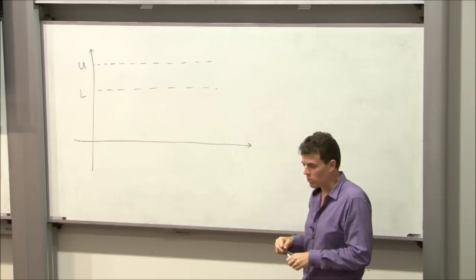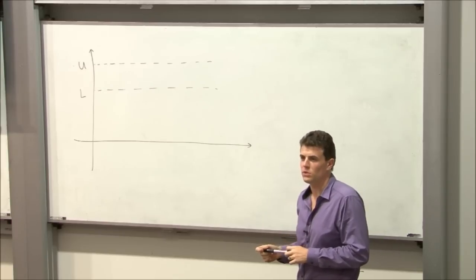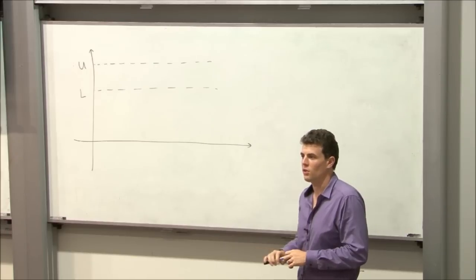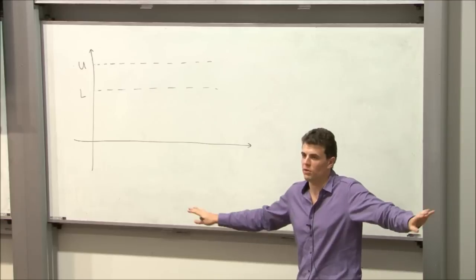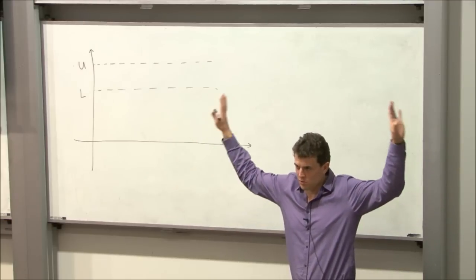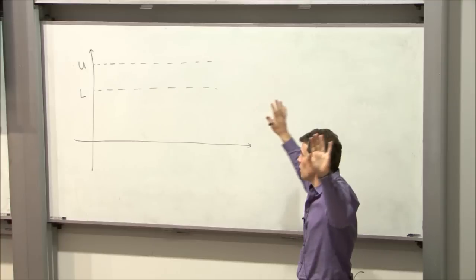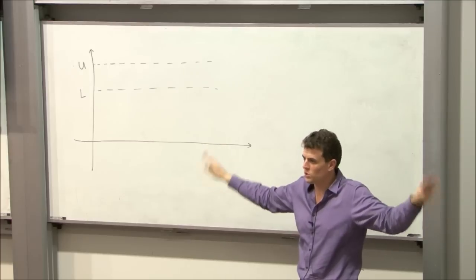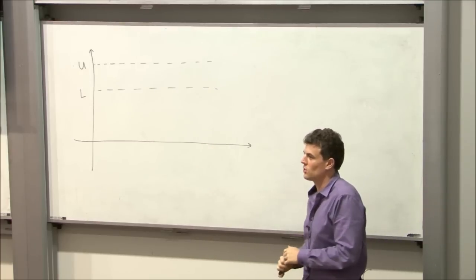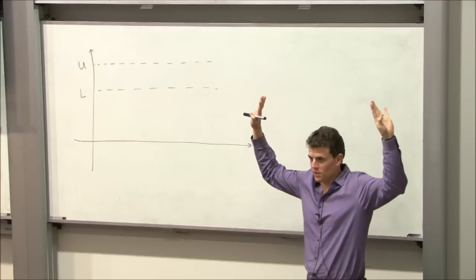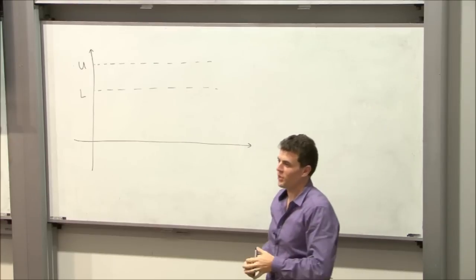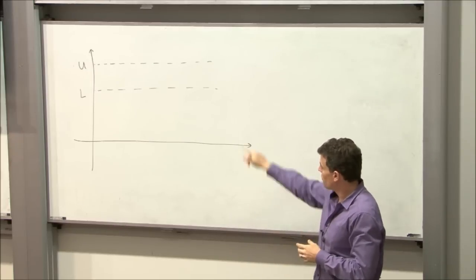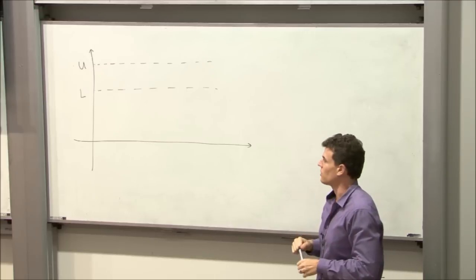Now, if you look up ultimate load tests on something like the 787, you can see these big aircraft that they put in a set of jigs, and they bend its wings up until they get to ultimate load. And if you think a bit of turbulence when the wings are moving around is a lot, the aircraft wings are nearly touching at the top before they snap them off the aircraft. So there's a lot of reserve capacity in these aircraft.